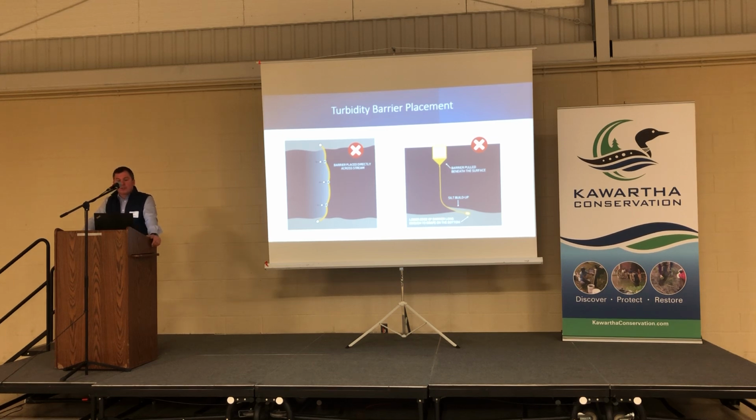The next version, slightly more robust, is designed for flows up to 0.13 meters per second. This still meets the OPSS specification, but it has an additional heavier flow material, and then it also has the aircraft cable and the hooks on the top, really to create a more robust, stronger duty type application. Suitable for depths up to 6 meters, and as short as 0.6 meters in depth. Again, connections can be with the quick links and the zip ties from one curtain connection to another to create a fairly continuous, fairly tight type of containment there.